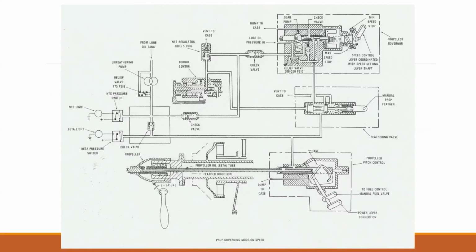They are able to activate the feathering valve in the case of an under torque condition. Under torque means the prop could potentially spin way too fast because we got a breeze, a tailwind or some other thing that can suddenly reduce load on the engine. We never want the propeller to drive the engine. We always want the engine to drive the propeller.